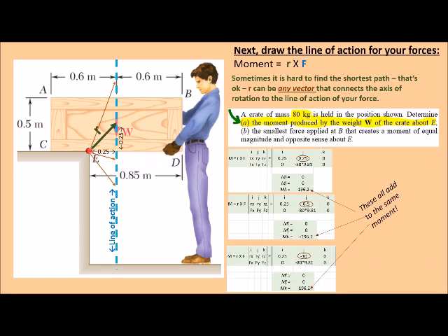An example showing all of the different possibilities of how we could have drawn this position vector, and it comes out to the same either time. So let's say instead of going straight out, we drew it to the center of the crate, and that makes sense because that's the center of mass, that's where the weight acts. So if we went to the right 0.25 and up 0.25, now I have those two components. I have to find a new position vector, but it's still going to our weight.